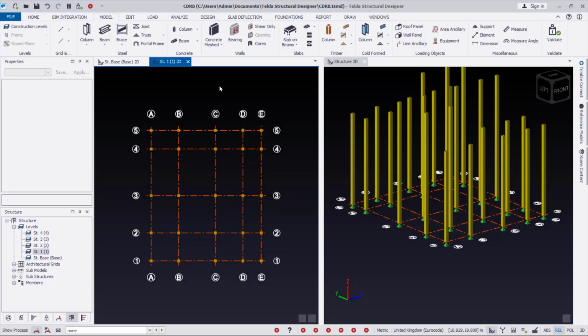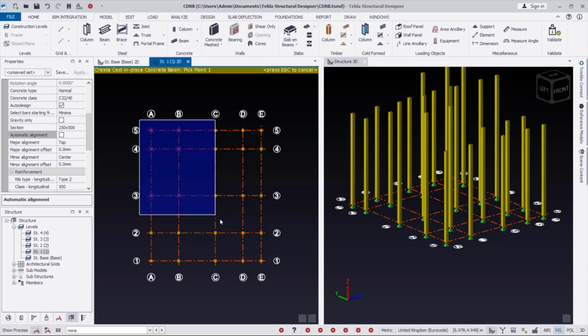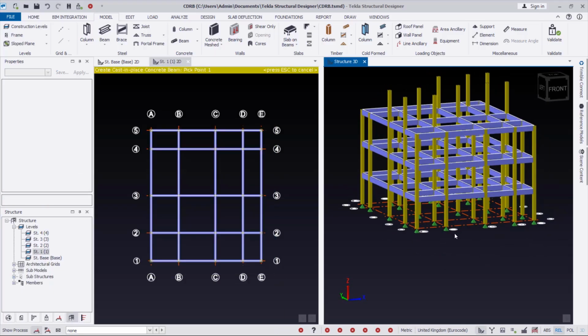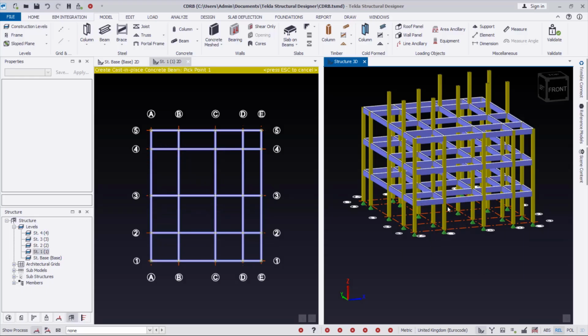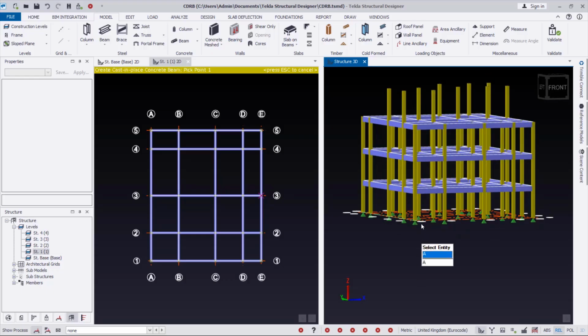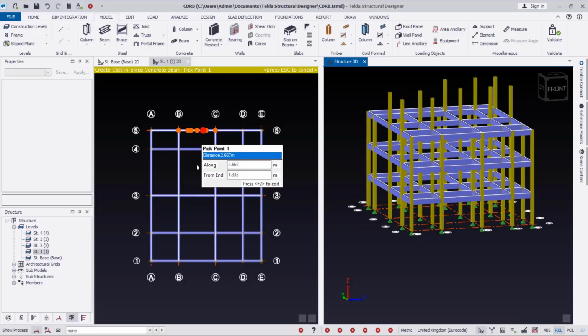From here, we will now place the reinforced concrete beam. So click in these provisions and then make sure all the settings are intact. After which uncheck these provisions and then do a window over this. Release your hands to place the beam successfully, just like this. You can see now the beam we placed on story 1 is being replicated on story 2 as well as story 3, because these stories are similar stories, except the topmost story that is unique. So that is what happened.